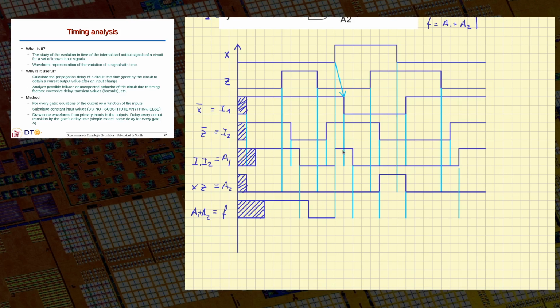So at this point I have a 1, 0. 1, 0 will make a 1, but with some delay, and will be 1. Now I have a 0, 0, so it will change to 0 again, but with some delay, and it will be 0 for some time, and then it's a 0, 1, so it will change to 1, but with some delay.